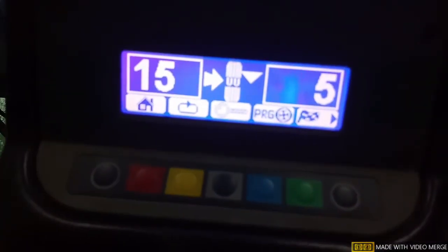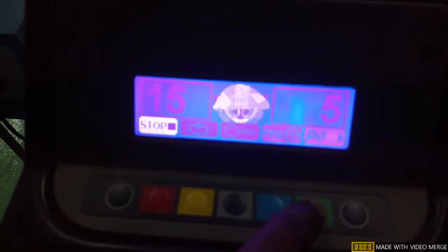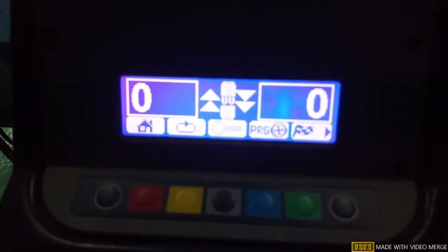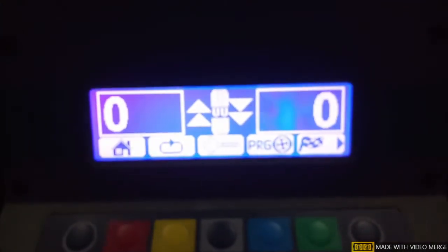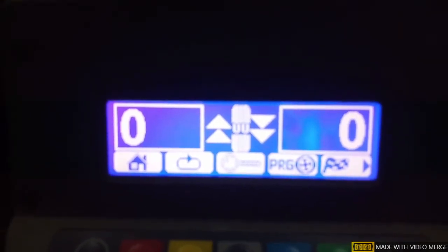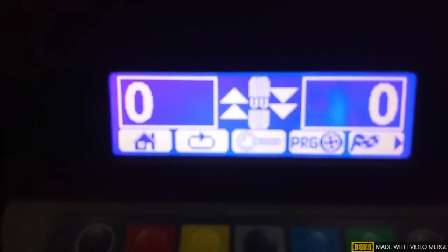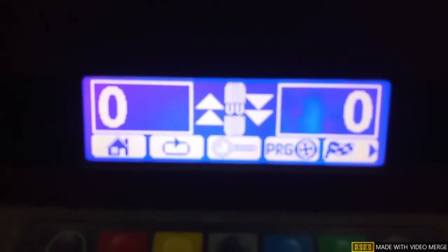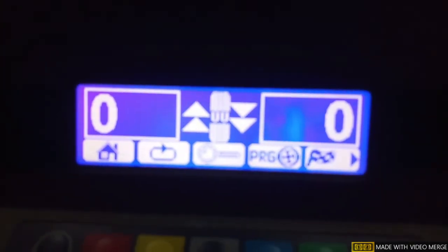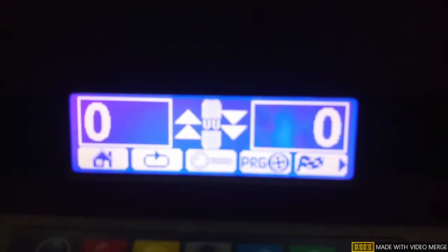Now finally, again pressing the green button, again we will see what happens to the weight. Okay, so now it is 0. So the conclusion is, once the unbalanced weight is shown on the screen, like the 45 grams or 50 grams shown earlier, those weights are added and it comes back to the neutralized 0. So now the wheel balancing is done.